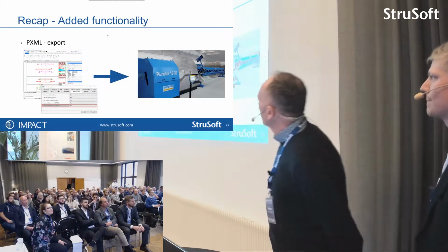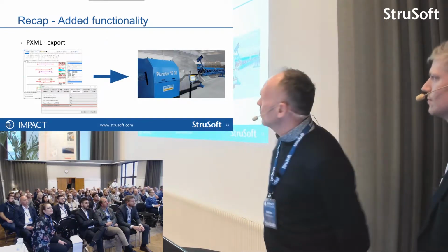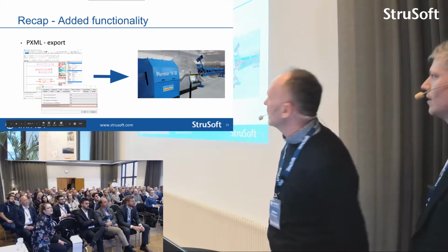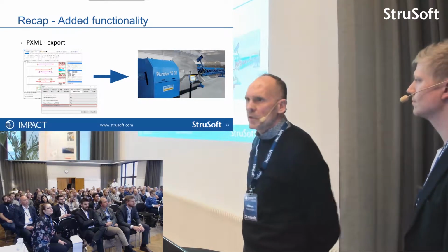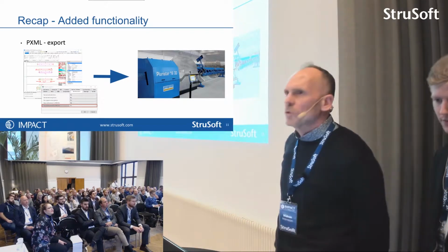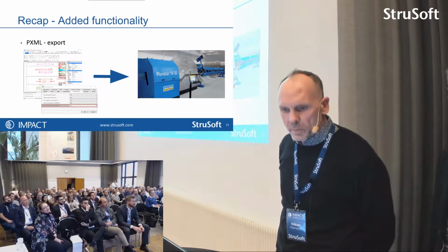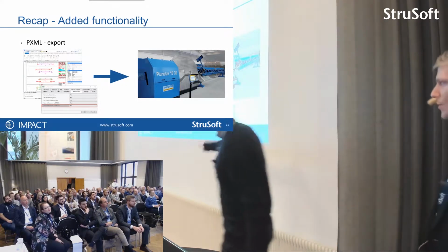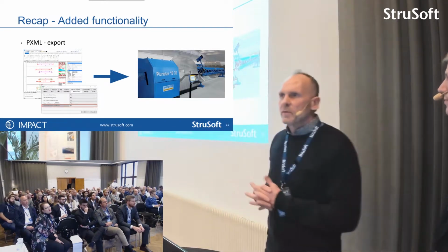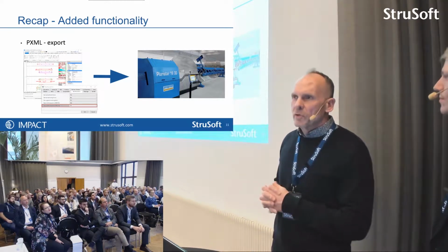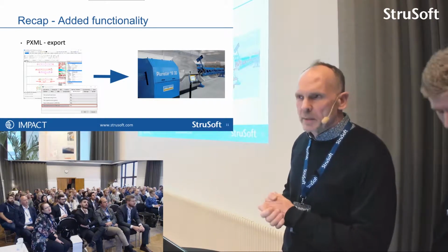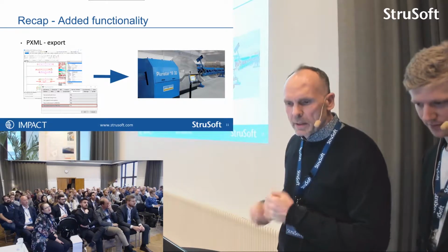Yes, we have also added PXML export from the PM, Project Manager. And what is PXML? PXML is the bending schedule for the bending machine. And you do this in two steps. First of all, you have to activate the setting in the project properties, Save reinforcement PXML file. So at the same time as you save a drawing, there will be a PXML file in the same folder as the drawing, in the drawing folder, and it will be named the same as the drawing, but with a PXML extension instead of DWG.